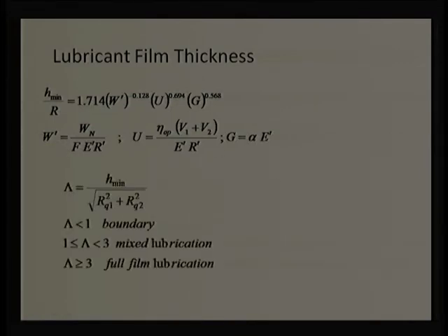Now, once we know the film thickness, we can find out a specific film thickness, which is going to decide whether the gear is under boundary lubrication, mixed lubrication, or elastohydrodynamic lubrication. I am leaving out the possibility of full film lubrication, because gears will not operate in full film lubrication. At most they can be operated in elastohydrodynamic lubrication, but we have this kind of a division.